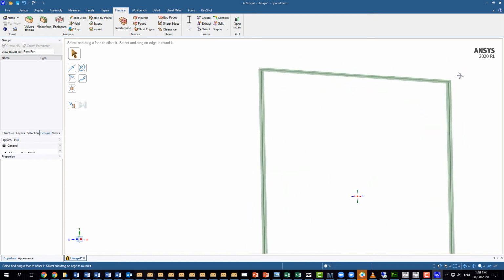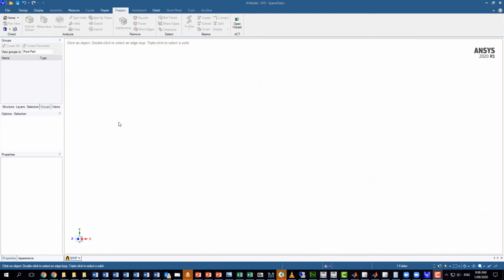That's your I-shaped beams. Just one more thing. In this particular problem, we do want the top beams and the side beams to be in a different profile. So we're going to need to create a new profile for the other type of beams. So again, just go into profile and I beam.